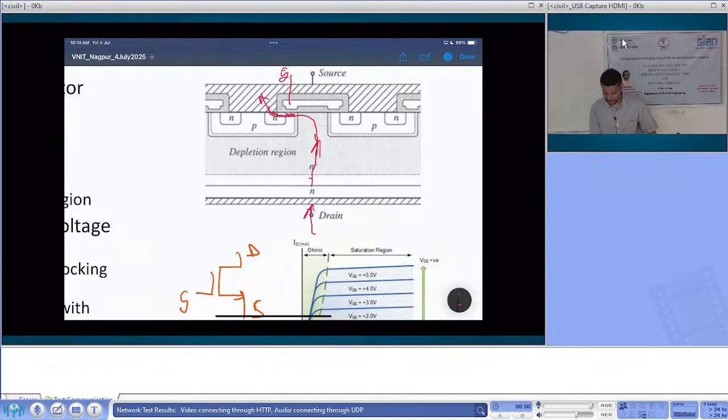And there is a body diode as well. So if you see, there is a body diode here anyways. But let's focus on the case when this MOSFET is off, right? That means you have removed the gate signal, and now there are no electrons here, right? In that case, you are still applying a positive voltage at drain with respect to the source, but now there are no electrons there, right? So what will happen is this device will try to block the positive voltage,